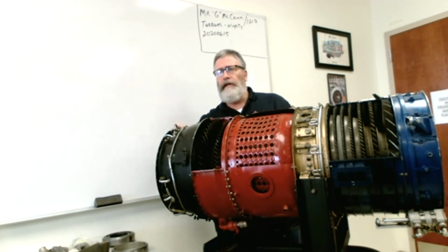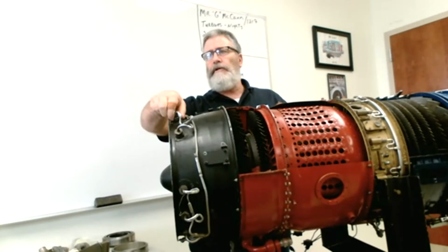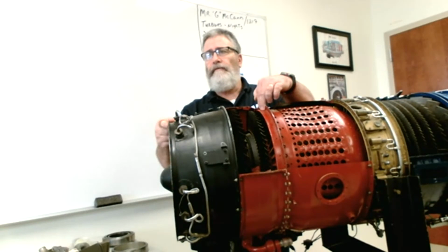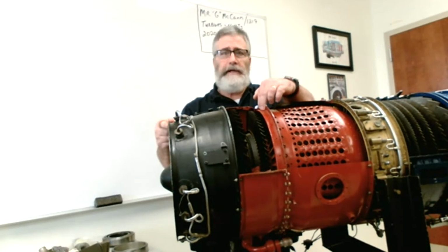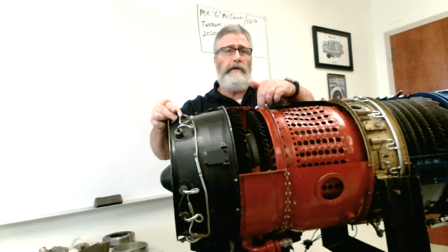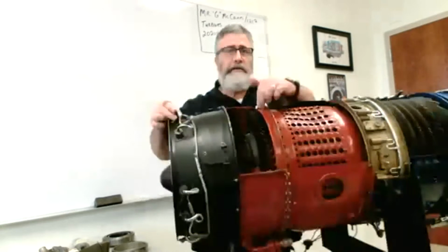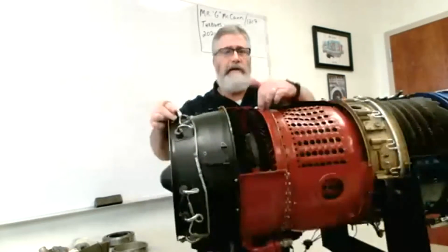Okay, as we get back to the exhaust section, I'm going to try to keep it simple. This engine utilizes what's called an EGT system, which stands for exhaust gas temperature. Now, we said that the first stage turbine nozzle is actually the hottest point in the engine. So, some manufacturers choose to put their temperature probes here, in which case it would not be called the EGT, the exhaust gas temperature, but it would be called the TIT, or the turbine inlet temperature. Now, this is very common, but you have to remember the temperature up here is very, very high. Like I said, 1,800 degrees Celsius.